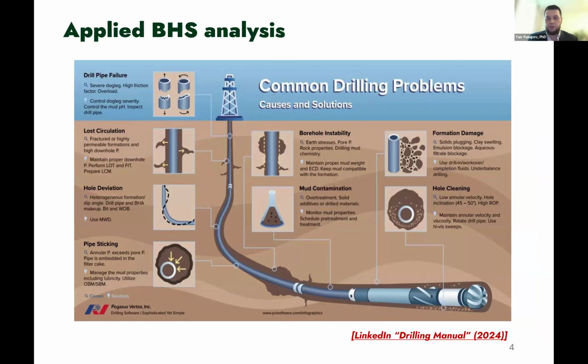During drilling and building of a well, especially drilling and backreaming out of hole on wireline, we can have many drilling events associated with loss of circulation, hole deviation, pipe sticking, mechanical or differential sticking, borehole instability, formation damage, casing damage, hole cleaning, and other dangerous drilling events. Geomechanics and adjacent disciplines are among the tools that can help us improve the process of drilling and building a well and make it less expensive and more productive.